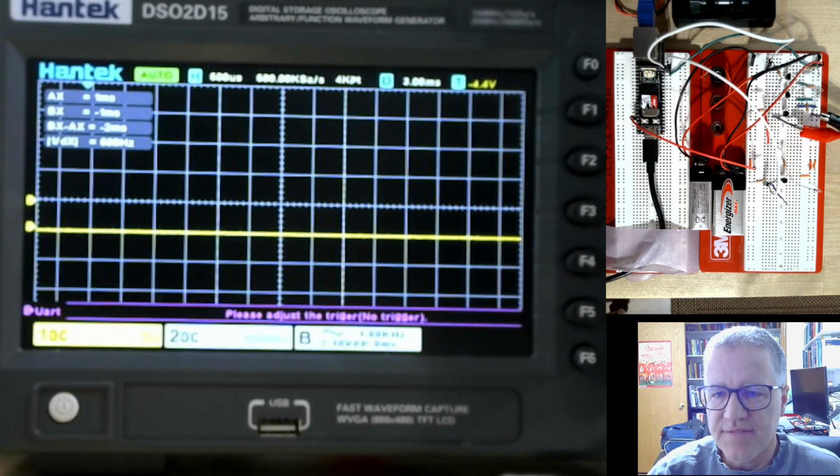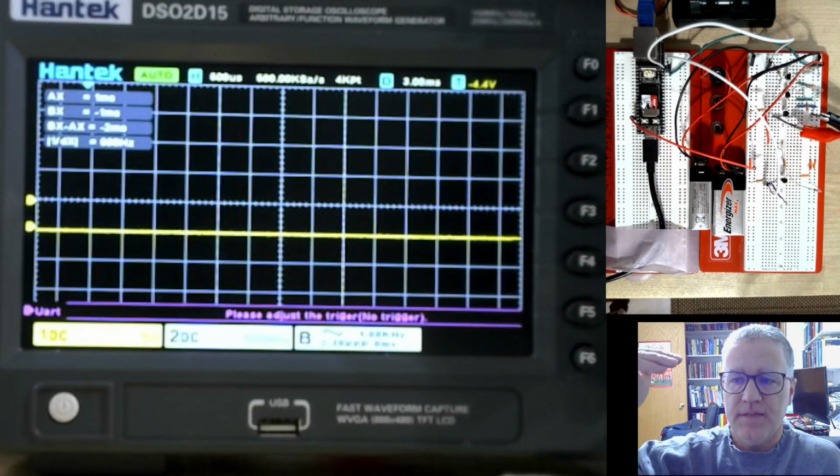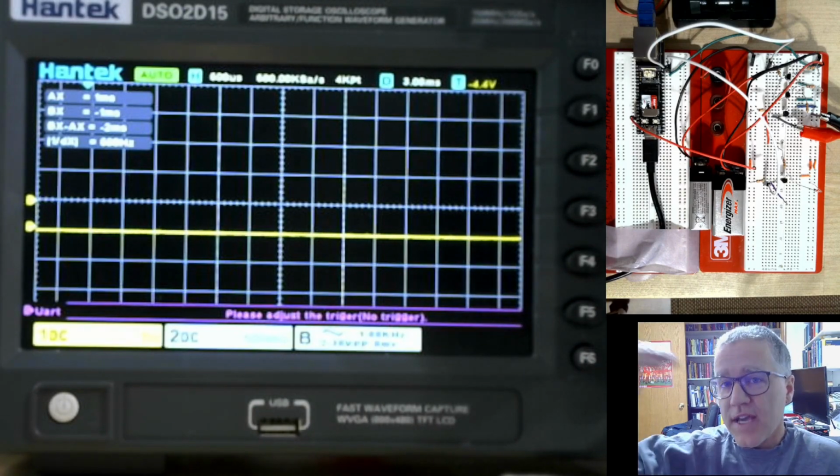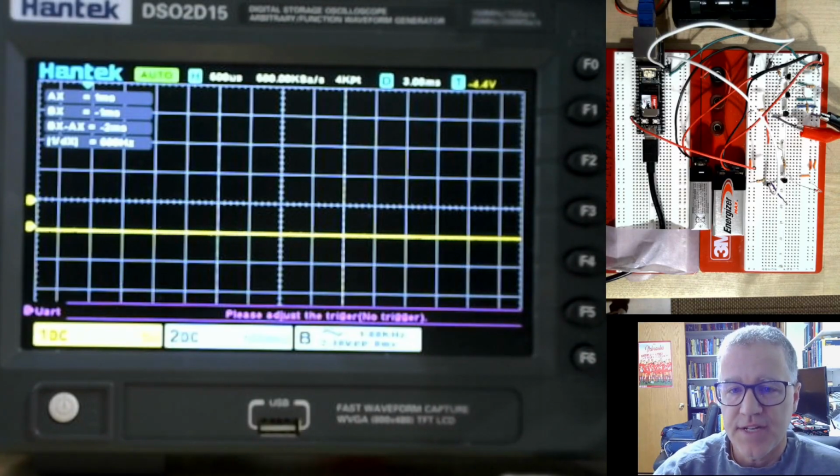You can kind of see the live data coming in. We know that in UART protocol, the idle state is high. In RS232, the idle state is -9, so we're sitting at -9 volts. It looks like this is the zero. It's not, it's actually up here. This is the trigger level. And so we'll send a character, and we'll see swings of approximately 18 volts here.